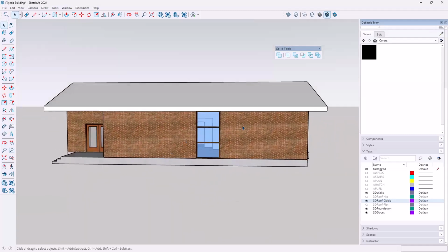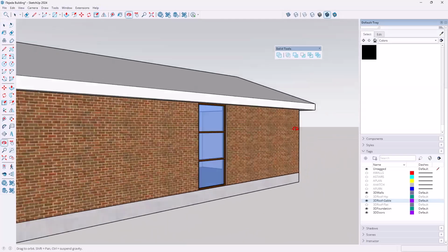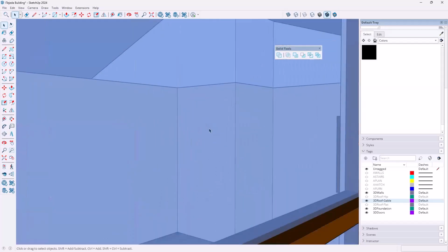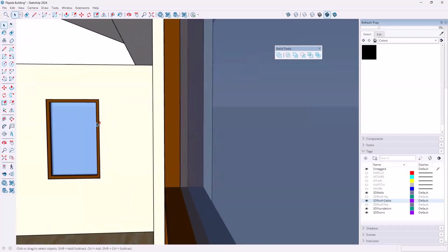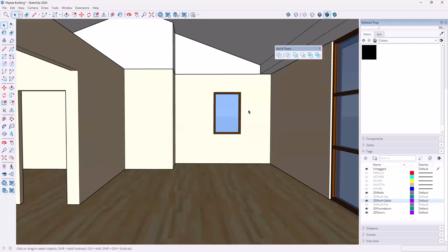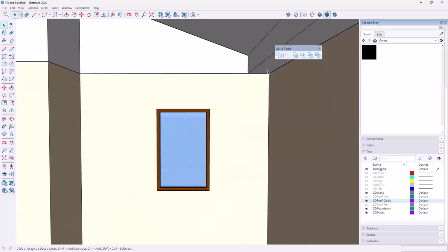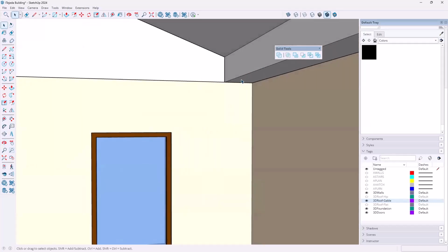Okay, so those are the different roof types. Keep that in mind, and then also be thinking about what you're going to do for your ceiling on the inside. So this is my roof right now. I'm going to orbit around. There we go. Get in there. And I may want to go with a flat roof. And if I do a flat roof, you'll see that this edge of my roof is touching on the bottom. So I may put in my ceiling and just drop the ceiling 1 inch. It's not a big deal.